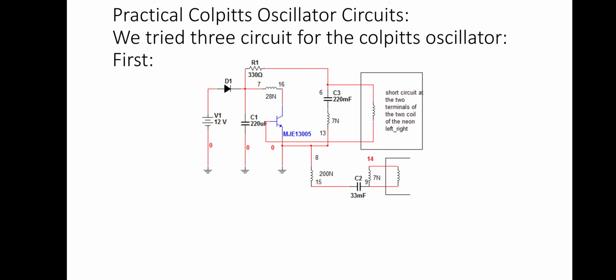In this we are using 3 circuits for Colpitts oscillator. It is the first one, and its construction is, let us first take a look at the circuit diagram of the Colpitts oscillator. In this we are using 3 resistors, R1 and R2 and RE. RE provides the necessary bias condition for the circuit, and the capacitor CE provides an AC ground, thereby preventing any signal degeneration. This also provides temperature stabilization.